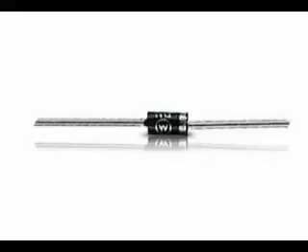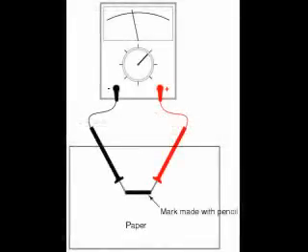Take a piece of paper and draw a very heavy black mark on it with a pencil, not a pen. Measure the resistance on the black strip with your meter, placing the probe tips at each end of the mark. Remember to try different ranges on the meter. Move the probe tips closer together on the black mark and note the change in resistance value. Does it increase or decrease with decreased probe spacing? If the results are inconsistent, you need to redraw the mark with more and heavier pencil strokes so it is consistent in density. What does this teach you about resistance versus length of a conductive material?